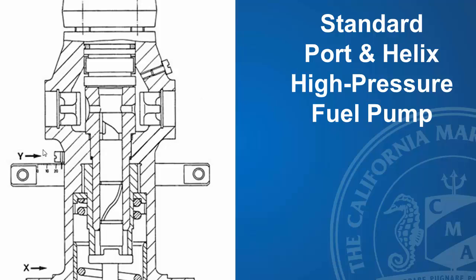Another point to mention within the discussion is when you look at the pump plunger, you'll notice that the pump plunger has to rise a certain amount before it closes the spill ports. And that's intentional, and that is an advantage to this pump, because I want that pump plunger to send a shock wave to the injector. You don't want to think of this so much as pushing fuel, but sending a shock wave.